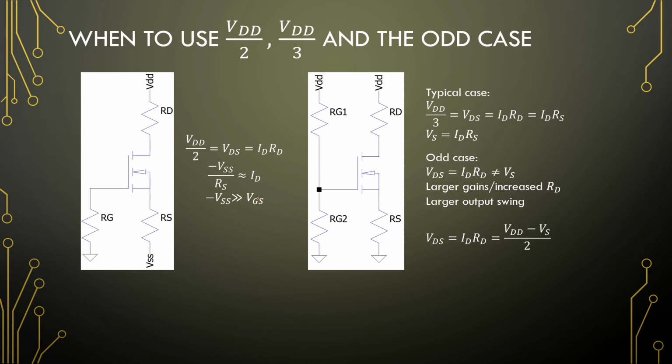So we only have two configurations that we can use for the common gate amplifier. So this is the dual rail where the input comes in here. So RS is then just responsible for the bias. RG is to provide a nice DC path for Kirchhoff's law here. And the drain resistor is responsible for the gain. And we have a voltage across those two to be the same, and that's VDD over 2.